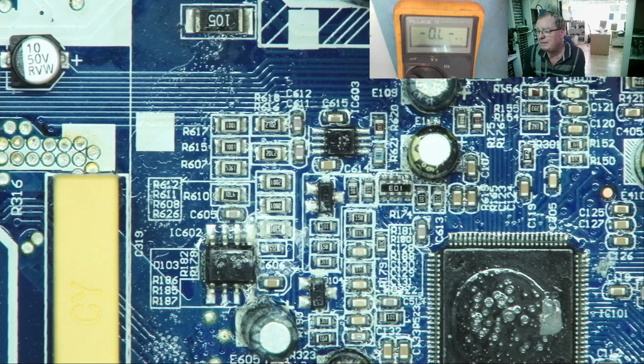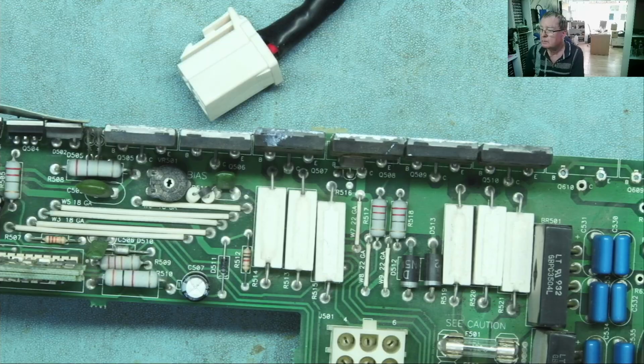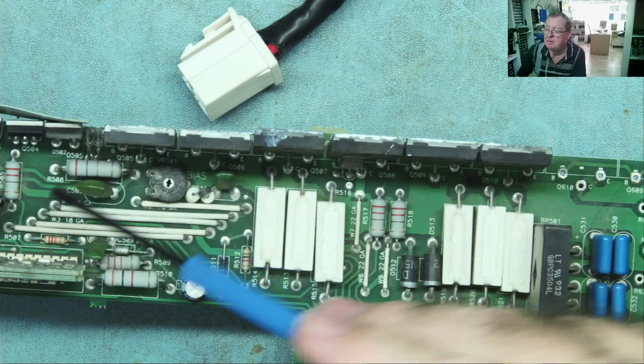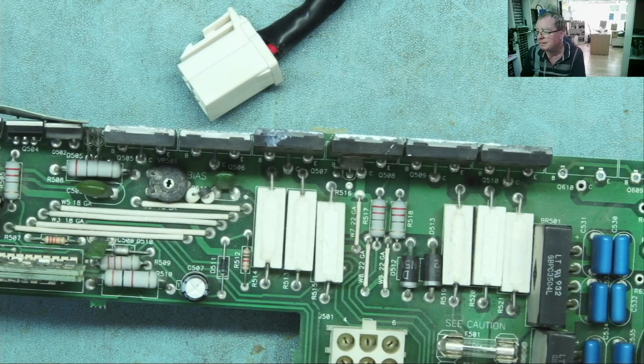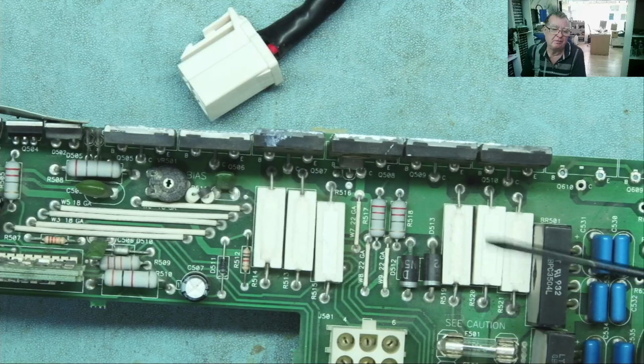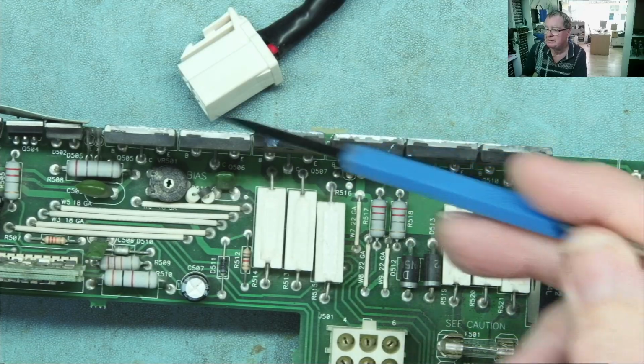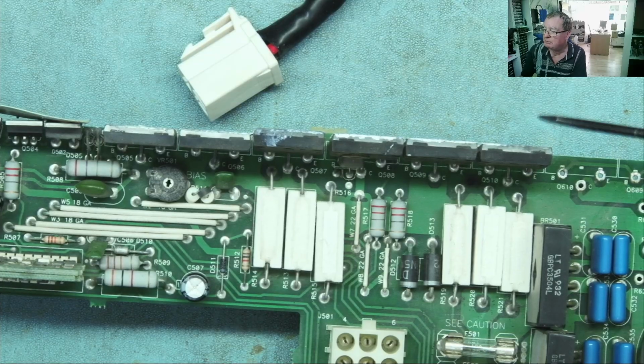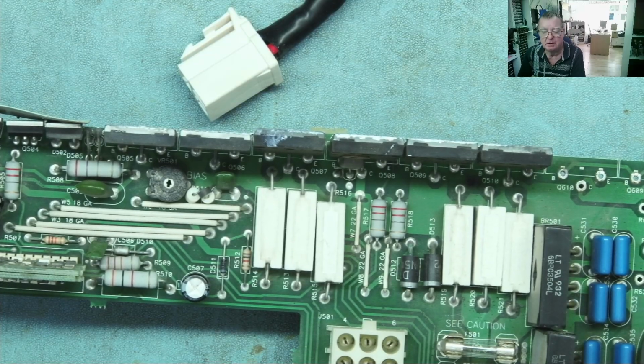The reason for that is low value resistors are generally passing quite a lot of current. And if they burn up, you can 99.9% of the time say they burnt up because something else failed, causing the resistor to pass too much current. That's why it burnt up. So resistors like these, if they're burnt or cracked or broken, they won't do that on their own. It's because whatever they're powering, in this case high powered transistors, have failed and gone short and taken the resistor with them. So that's what happens to low value resistors when they fail.